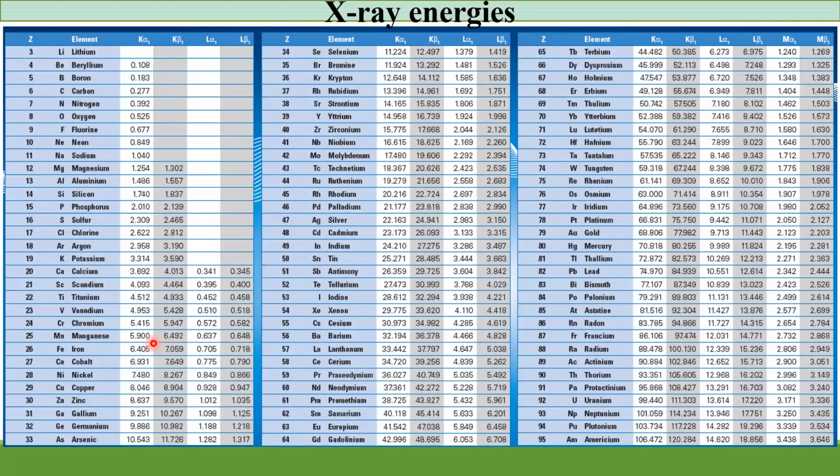Of course, recent advanced EDS detectors are trying to resolve those things. I will show a few practical software examples later on if we have time. But in other terms, you need to think over it. You have the peak, but you cannot define whether it is from manganese. Then if you just do automatic mapping, the system will give some calculation like chromium 50% and manganese 30% and other elements with some percentages. Then you will write that down, and that will be an error.